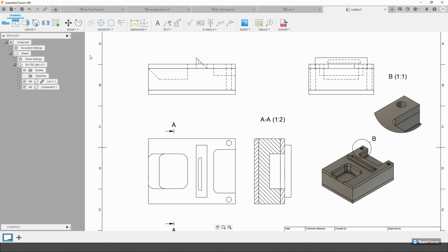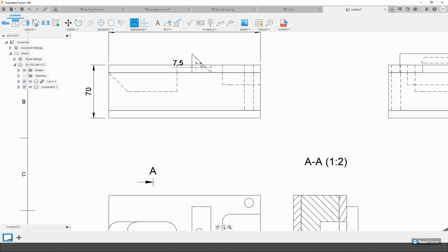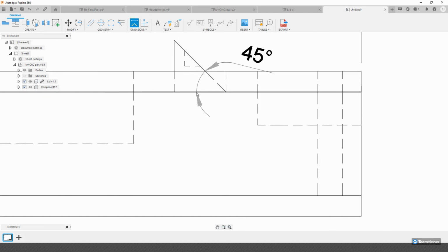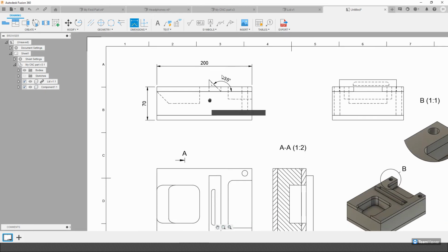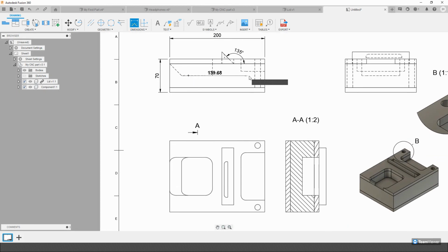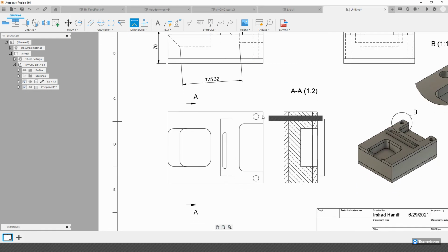And then of course, the most important thing we want to do is give center lines, bend lines, and annotations. Annotations are simply a matter of clicking point to point for linear dimensions, like so, or clicking between, for example, two lines to give an angle, maybe that angle, clicking points to give certain areas.